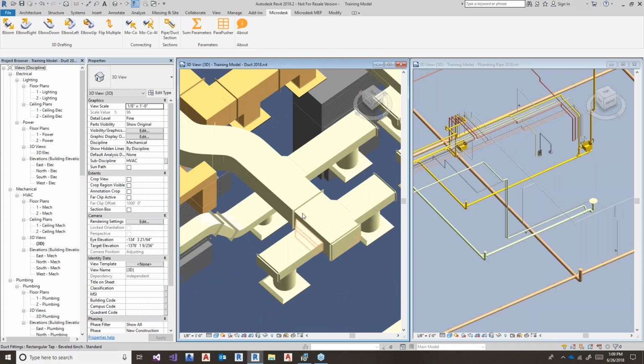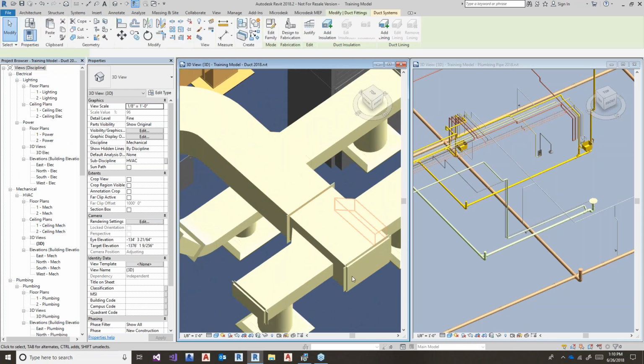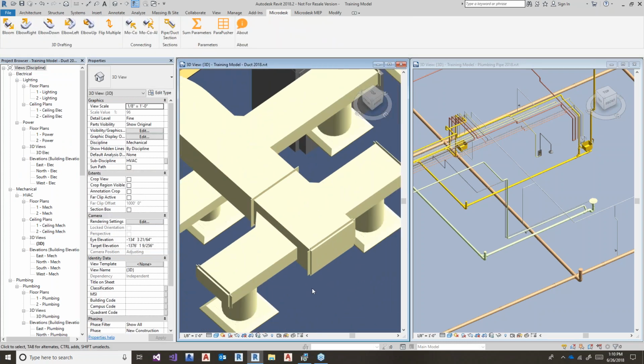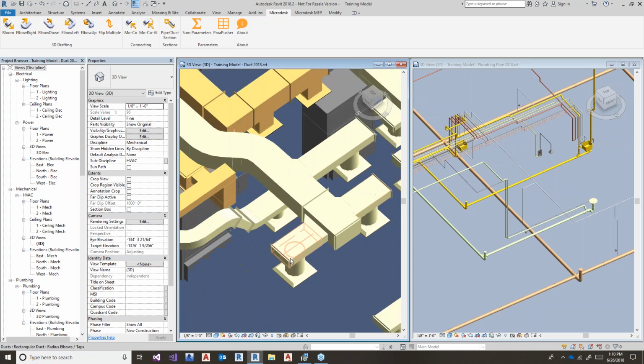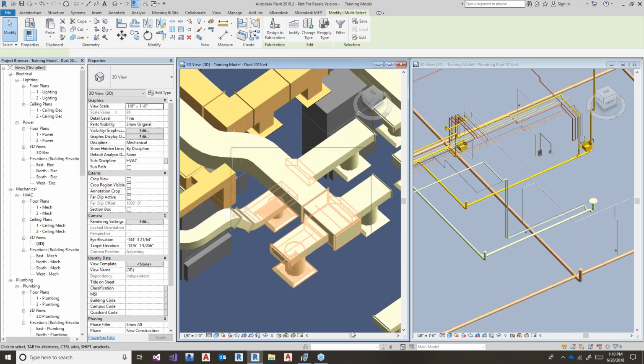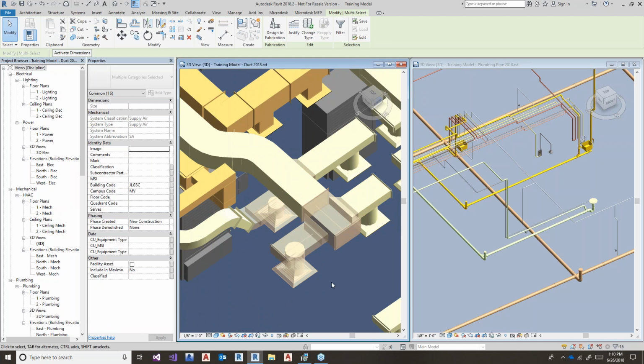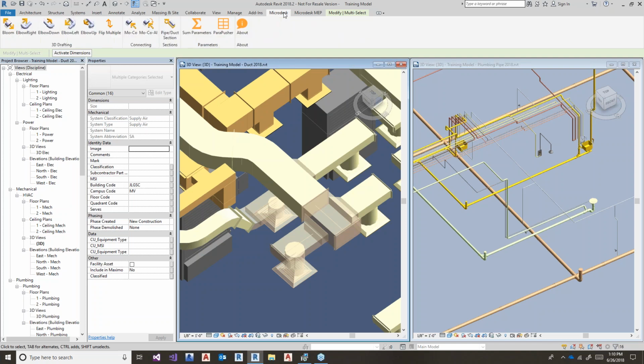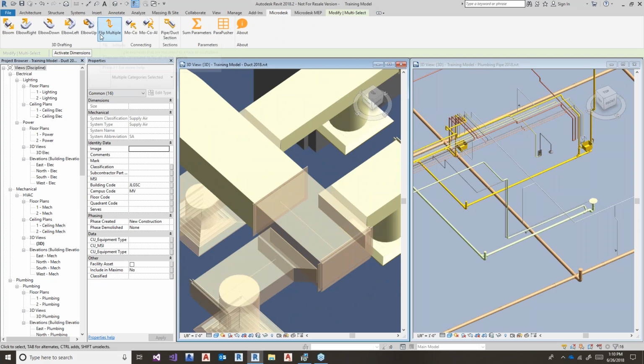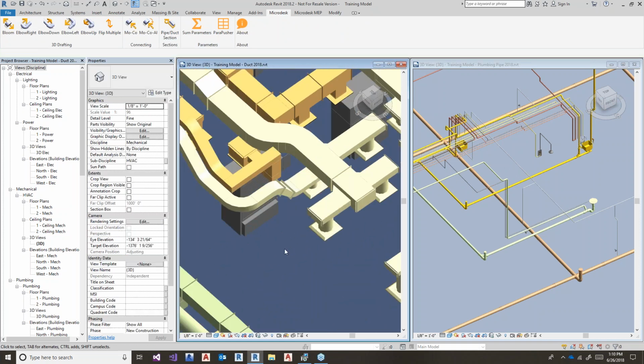Just really quick, if I don't get to it again, Eric was showing you that flip multiple command, and things like taps on ducts actually behave like hosted families. The tool itself does something pretty cool where it will filter out non-hosted families. That allows me to draw a window select around things that include takeoffs and taps, and say we want to flip multiple. The selection set doesn't go away, but you can see all of the taps in that selection set get flipped. The duct, and these non-hosted air terminals, get ignored, so nothing gets broken.